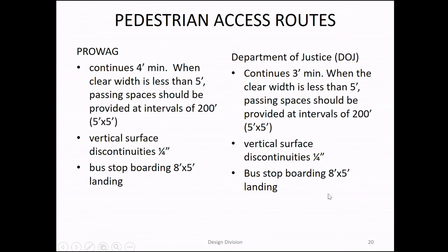Now, bus stops, I don't know if most of us really pay too much attention to it, but you need to have an 8 by 5 landing. This is especially because of the front door of the bus, because they have this ramp that drops down. That ramp is 4 feet long, so you need about another 4 feet for this person to get off the ramp and turn. So you need a landing about 8 by 5. That is in the parkway, bus stops, yes.